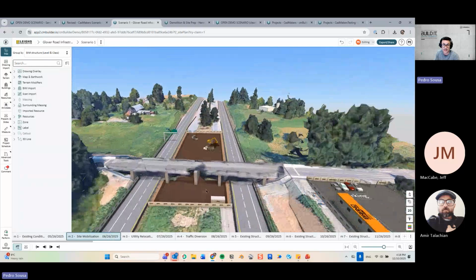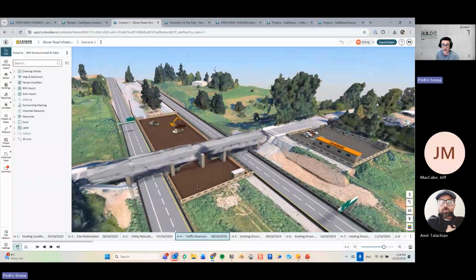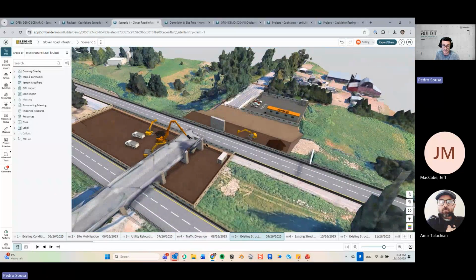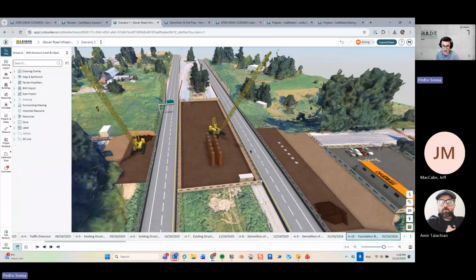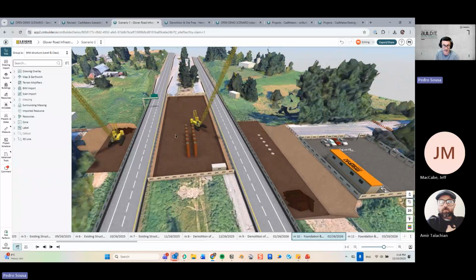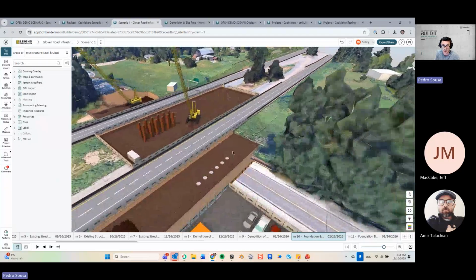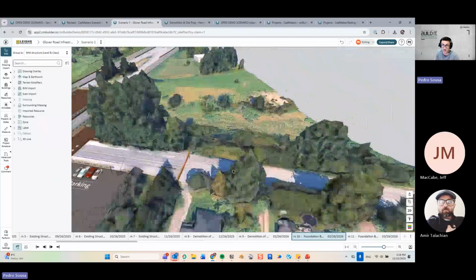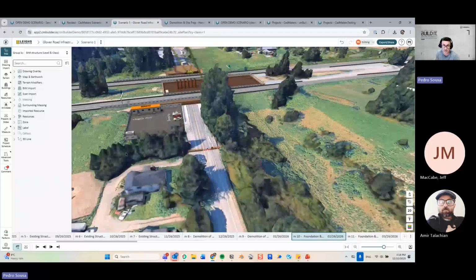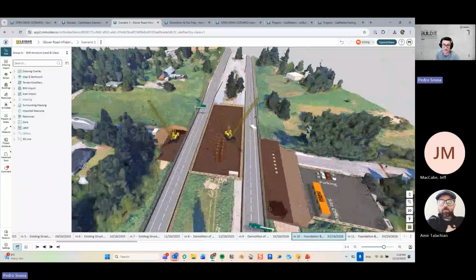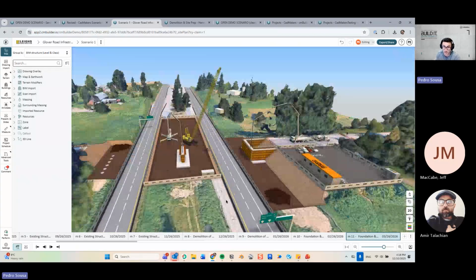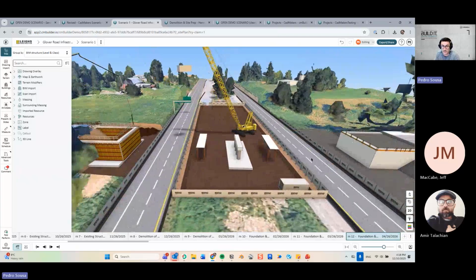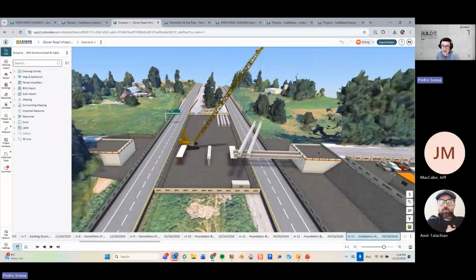So if I navigate through this, I will see the whole process of how the team went through the demolition stages, the execution of new structural parts, the placement of cranes, the blocking of roads. There's a blocking over here, there's a blocking down there, and all of that, showing all the types of overhangs that I'm going to have, the formwork that I'm going to be using, where I'm going to be working first, the backfill for these retaining walls, and so on and so forth, right?